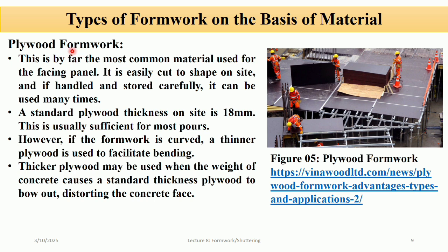Plywood formwork. So it is a type of formwork that is made from plywood, and it is used to hold concrete in place during the construction process. The purpose of providing plywood formwork is that it provides a smooth finish, it achieves accurate shapes, it supports concrete until it sets and gains strength, and it reduces the labor cost. It can be reused multiple times, increasing efficiency and reducing waste.